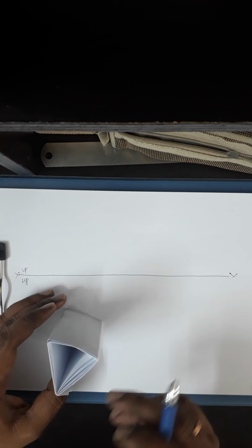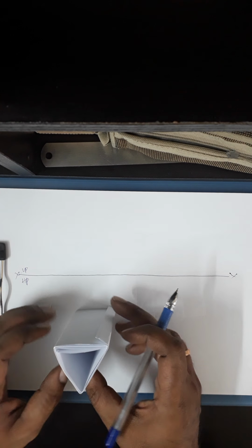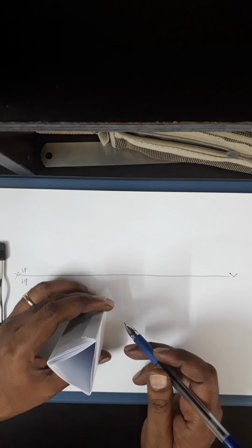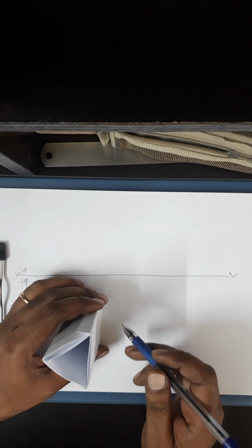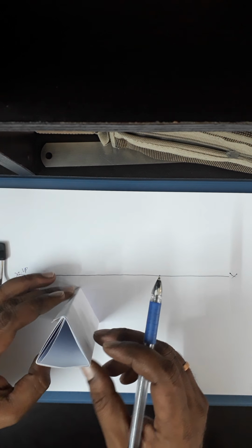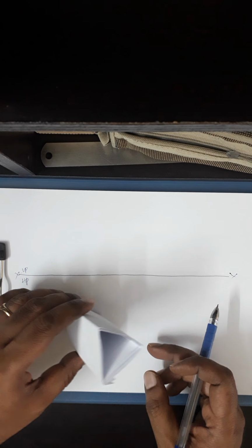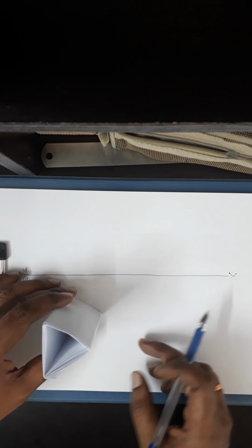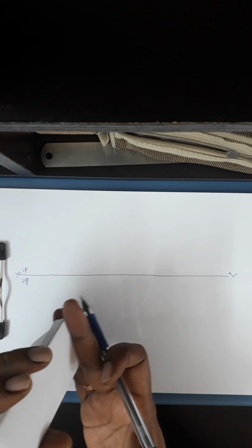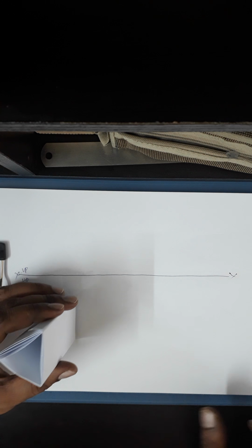then we're going to have two conditions in most of the problems. So when the axis is inclined to HP and parallel to VP, it will rest on one of its base edges on HP or rest on one of its base corners on HP. Because when I tilt, I can tilt about this corner, you can see, or tilt about this edge. So in these two conditions, you'll find the problems. Okay. So I'll go for the first case.